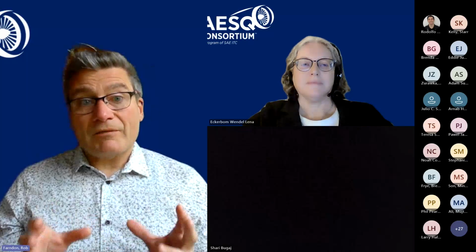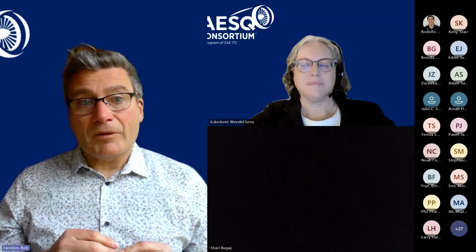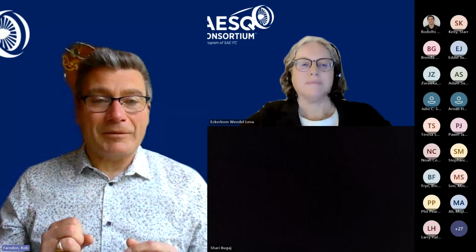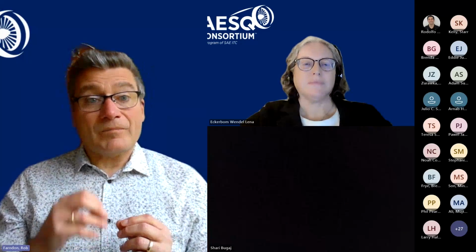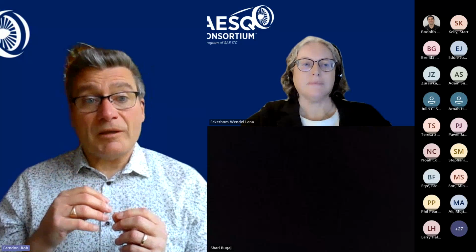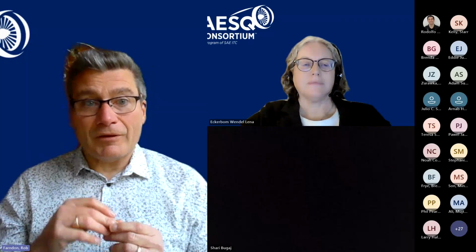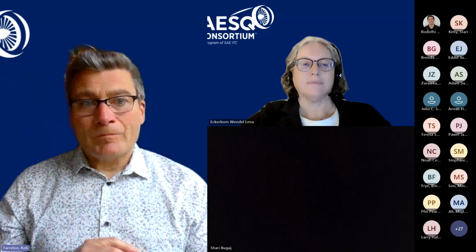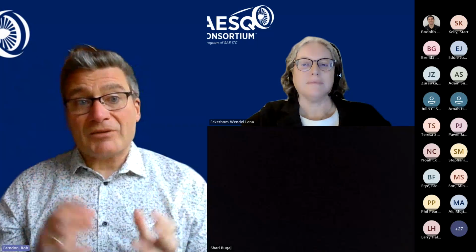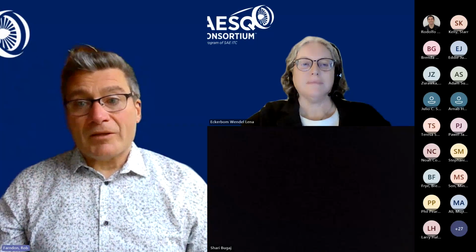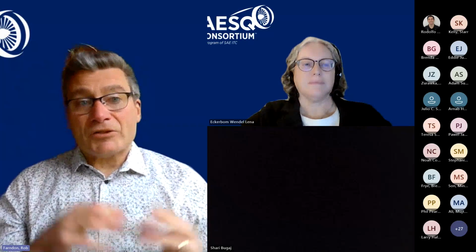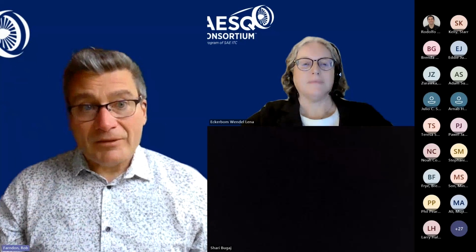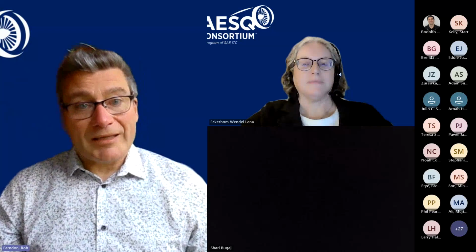Similarly, if you have a DFMEA that has a failure mode, we're talking about a bottom-up identification of a failure mode and effect here. In order to be effective inside a DFMEA, if you're going to work out what the severity is, what the system level impact is, you need to understand the system architecture, because a redundancy in a structure, let's say, will downgrade the effect that a particular failure mode has.